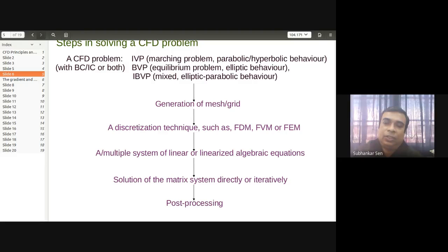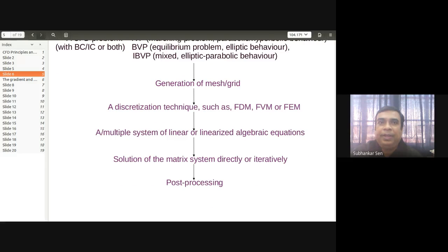So this matrix equation system up to this much is the CFD approach. Starting from this problem up to generation of the governing equations, this portion is known as CFD. After you get this Ax = b system, then you can solve for x from x = A inverse b, by direct methods or by iterative methods.